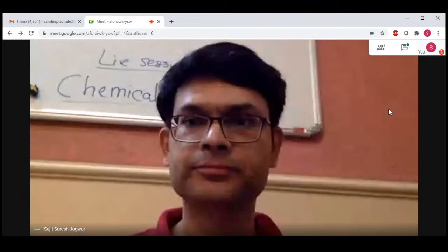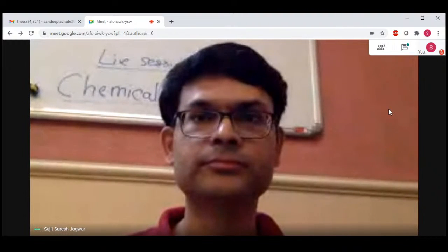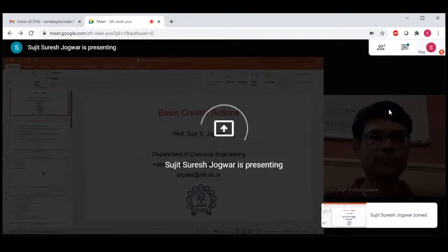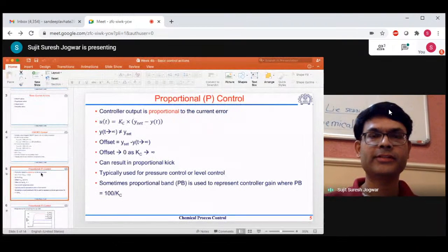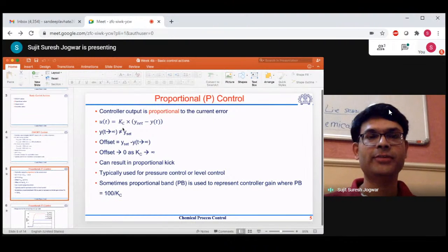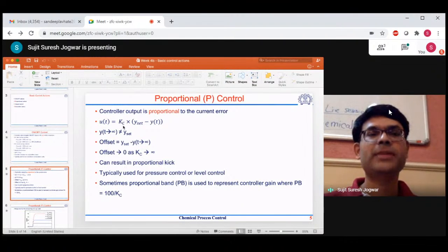Okay, let us take this very simple controller like a P controller. Now, when you say controller gain being positive or negative, I'm talking about this Kc being positive or negative. So how do you decide whether Kc has to be positive or negative? And that has its implications. So it depends on the process gain or the overall process gain.